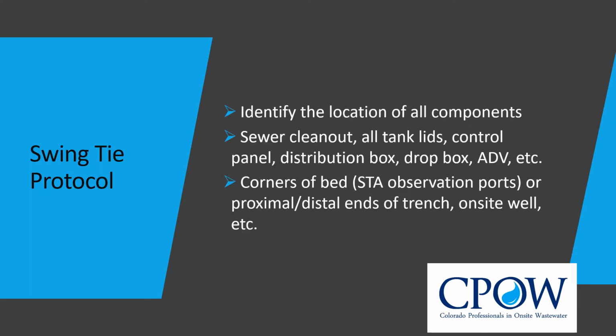Identify in your drawing the locations that the swing tie measurements are originating. An example would be the corners of a house. Also identify the OWTS component that is being located. Make sure to properly label A and B or 1 and 2 corners on the drawing in order to properly duplicate the measurements. Again, take measurements and elevation for record drawing prior to backfill when possible.